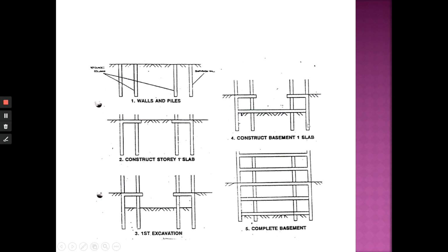Okay, how they want to go about it. Sometimes they also use it. Okay. For example, when they did the basement for services in UTP, our neighbor, University Technology Petronas, half of the slope was open cut and the other side was cut and cover. Okay, they mix different techniques. It can be considered as composite method as well.